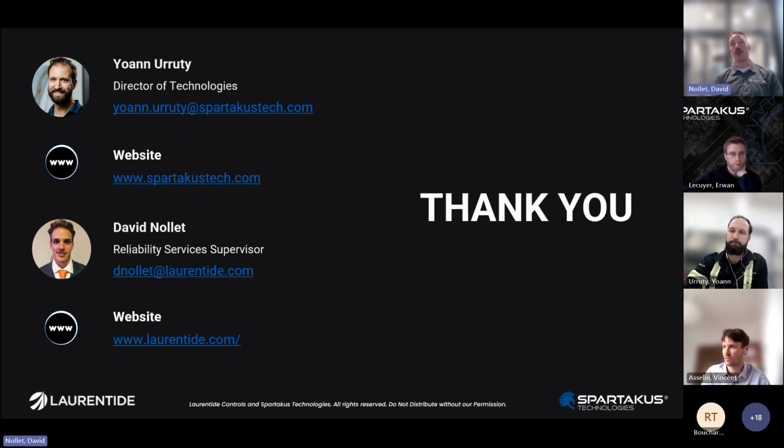It's that if you don't have the documentation, and ideally in digital format makes it a lot easier to work with, then you're stuck with doing field validation, field master data, which can definitely be worthwhile, but is very labor intensive. Now you're talking about walking down the line. Maybe you take P&IDs and you're validating whether it's matching your P&IDs, but you're walking down the line. You're trying to build an asset hierarchy based on what is physically installed. It's easier to miss things. You might end up with more of a spatial structure than a functional structure, which can work, but has certain disadvantages.